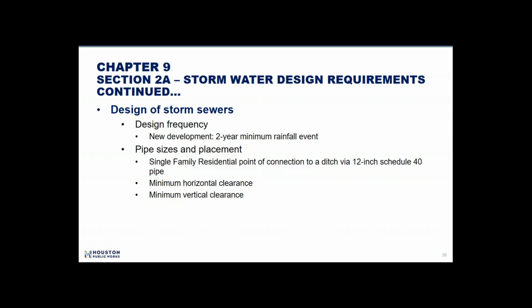The second thing is siphons. Siphons are also a major headache for our stormwater maintenance group. Blockages get into the system, or are basically created in the system. Some people have offered to do a maintenance agreement. That doesn't really help. If they're blocked at the time of a storm, it didn't help.